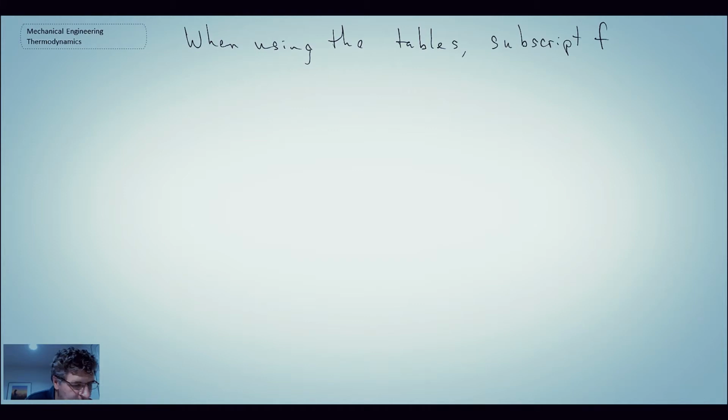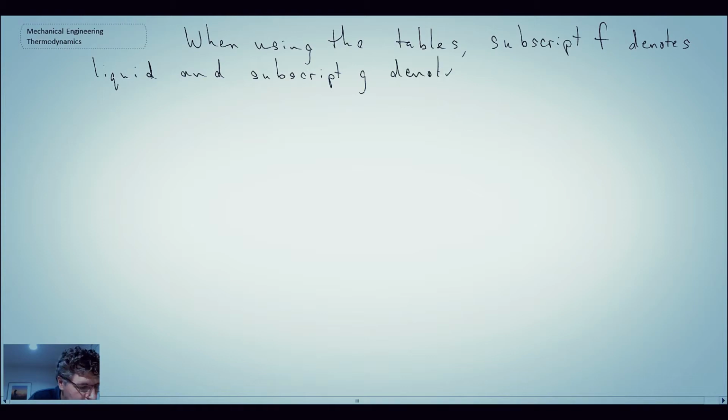Now, another thing I should say about the tables that we just presented: we talk about f and g. When using the tables, subscript f denotes saturated liquid, and subscript g denotes saturated vapor.